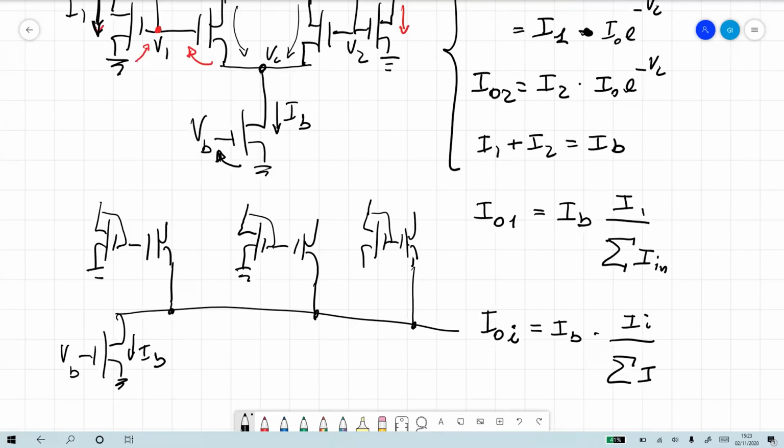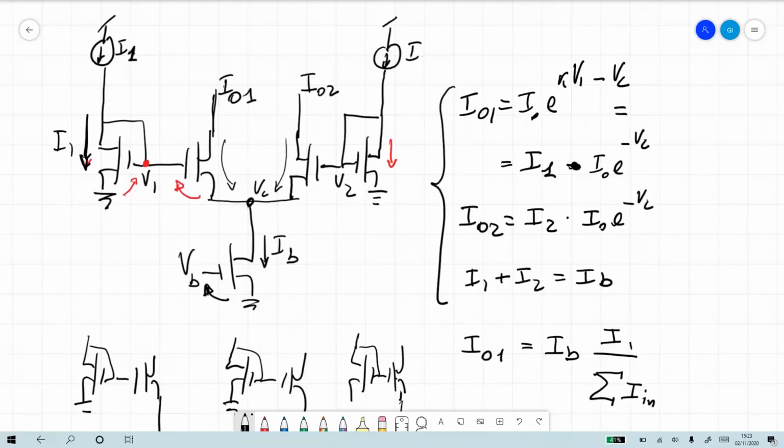So again, this is from Barry Gilbert, but he invented it for bipolars, but we can do it with subthreshold transistors. In this case, we did take into account the kappa, and there is no problem with the kappa. So in this case, we didn't use the translinear principle. We just did everything using the equations. And you actually caught me, you even found a mistake. But this last slide here is the correct one. So it's really a pure normalizer circuit. It's really helpful.